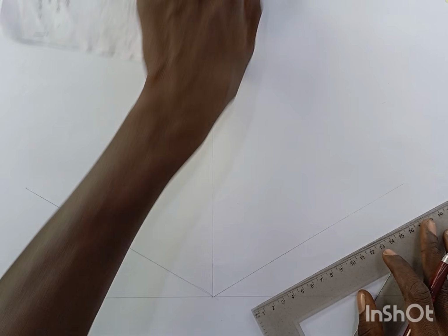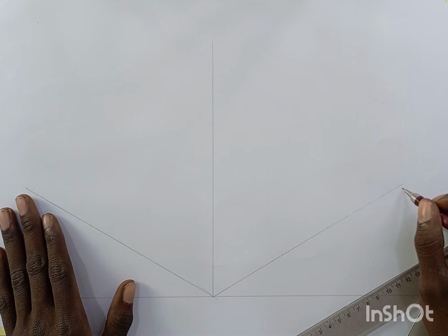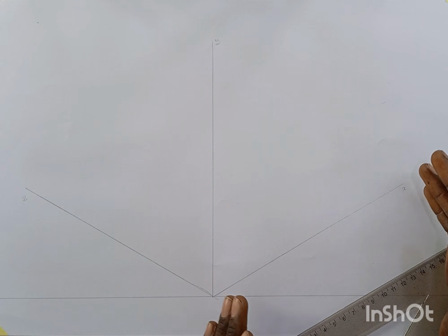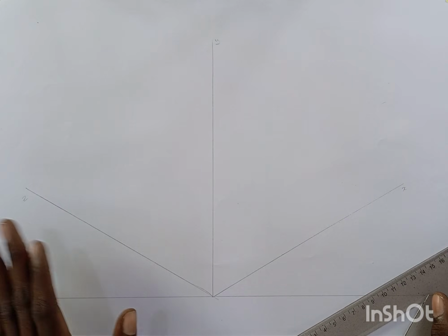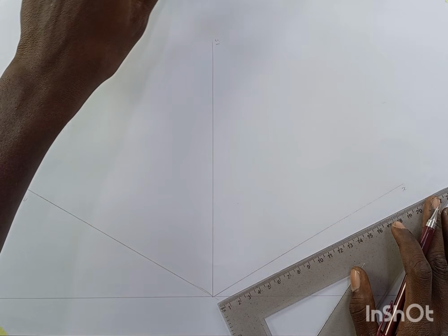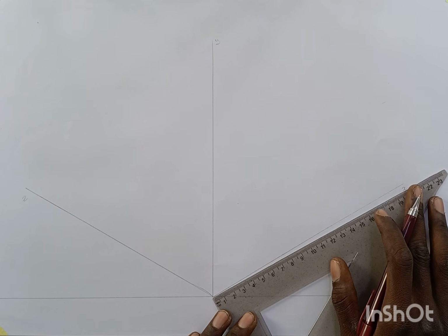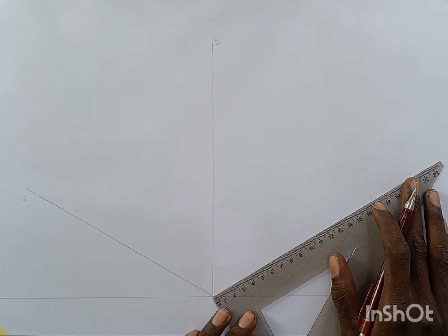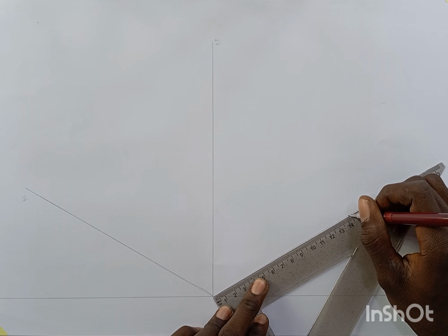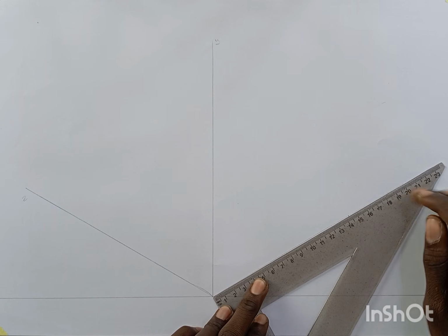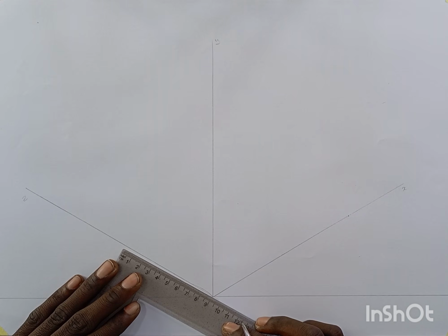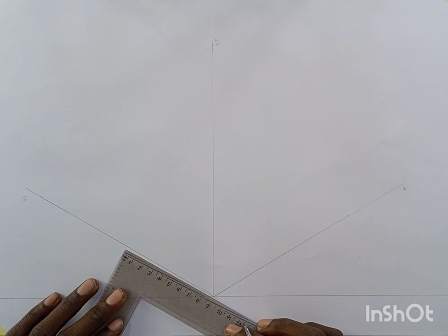Okay, now we dive into the work. We now measure, as we said earlier, this is our x-axis, this is the z-axis, and this is the y-axis. Across the x-axis, we put our length there, on the z-axis, we measure our width, and for the y-axis, that's where we make our height. So the length here given is 142. So now I'm going to measure 142 here, which is 14.2. This is our total length.